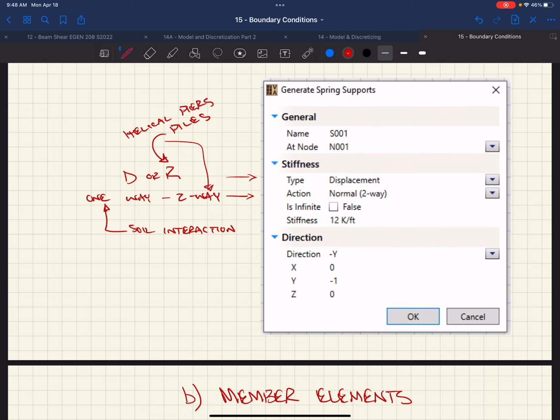So then you get a geotech that comes in and says, okay, your lateral resistance of these piles is this, and this would be your stiffness, right? So you end up getting a consultant in that gives you more of that information. I think helical was mentioned only when you can't do the other ones, like it's softer on the soil and you're not vibrating the buildings around it.